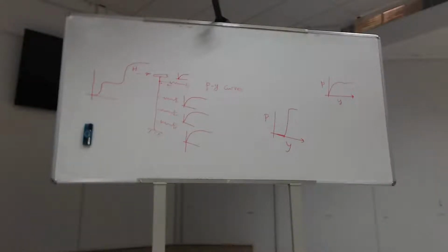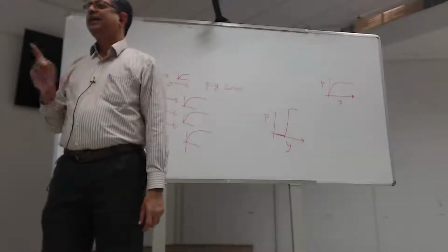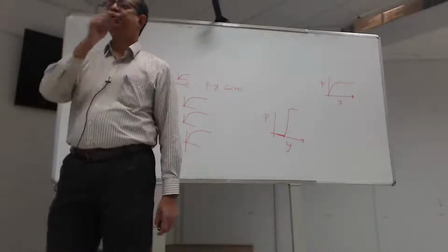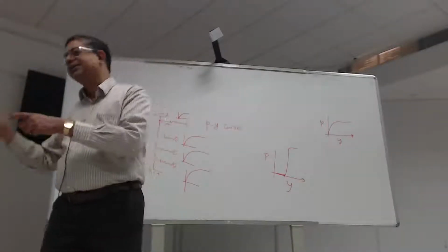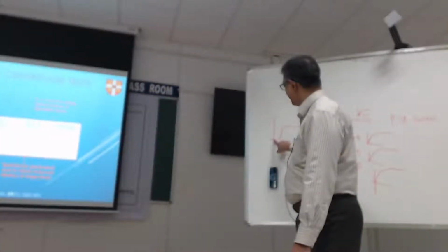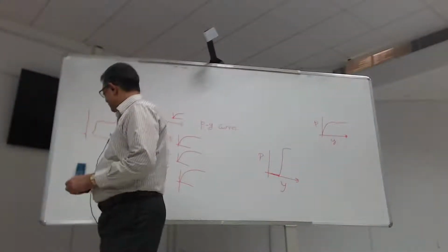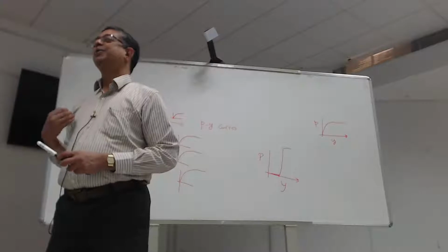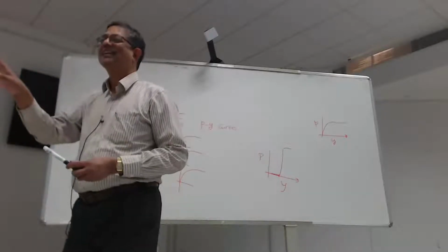This, we ignored this part here because we're not doing laterally loaded tests. Here, we are applying axial load and letting the thing kick off. And as I showed you from the data we got from the LVDT, pile buckling is an instability. Instabilities are always a runaway failure, which means I will not have that bit. In fact, it should be starting as shown there. Whereas laterally loading a pile, centrifuge or otherwise, would require a certain amount of strain for it to mobilize its stiffness. That's the difference. Here you're kicking the thing, whereas there you're gently pushing it. Two different things.